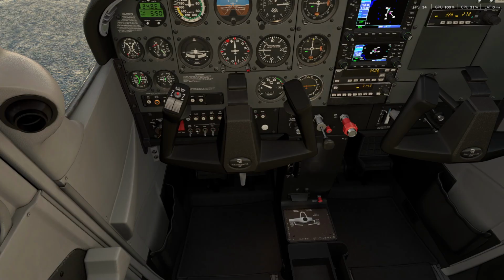Confirm the elevator trim is not moving. Again, pull the right-hand switch aft to the up position and hold. Confirm the elevator trim is not moving. Then release the switch and verify the right red PR light above the autopilot button, which I don't actually see happening, but that's fine.